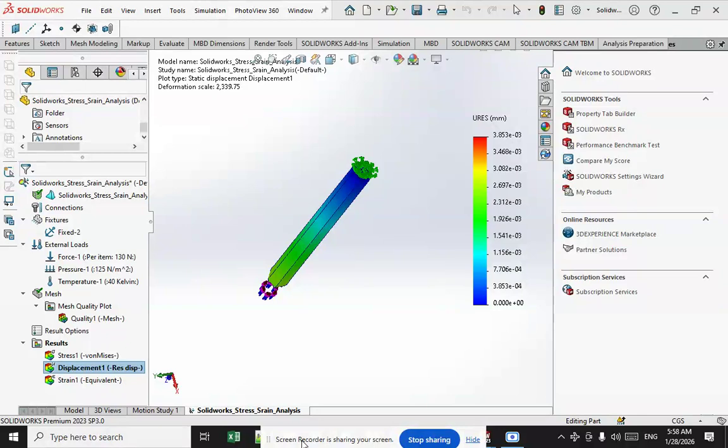The chapter of simplification. Stress analysis is simplified when the physical dimensions and the distribution of loads allow the structure to be treated as one or two-dimensional. In the analysis of a bridge, each three-dimensional structure may be idealized as a single planar structure, if all forces are acting in the plane of the trusses of the bridge.